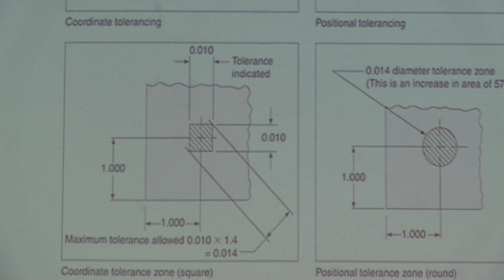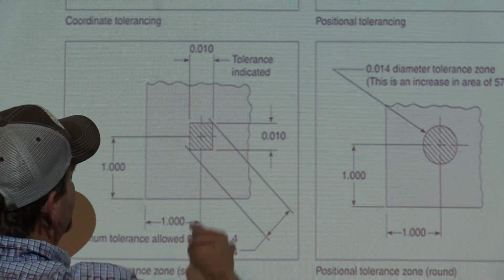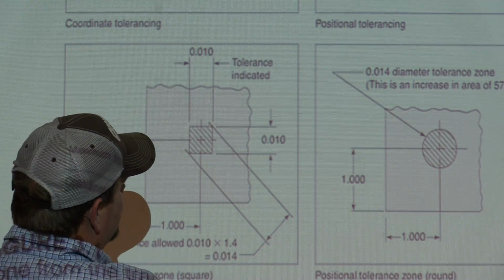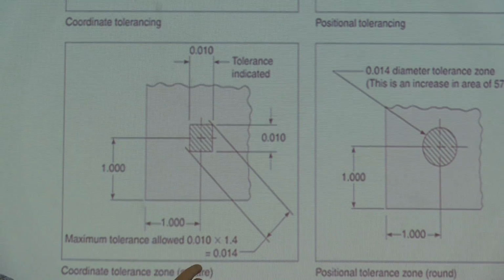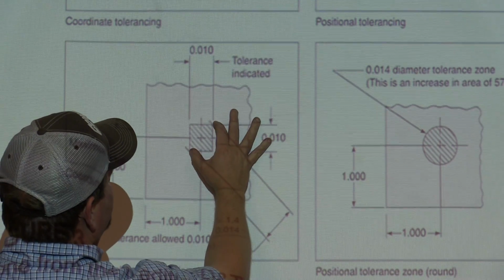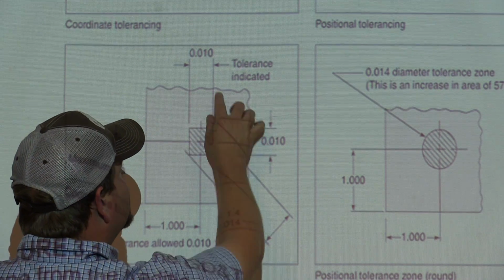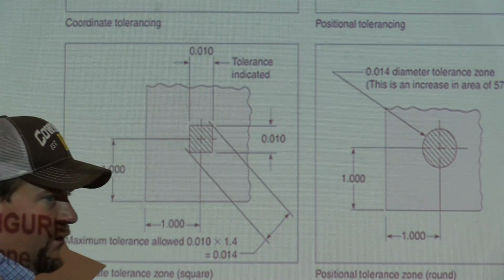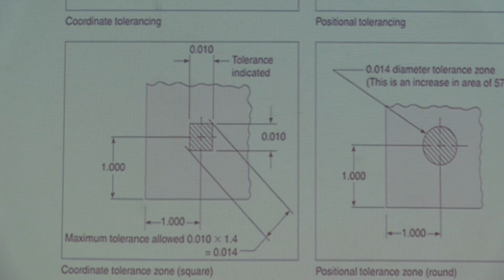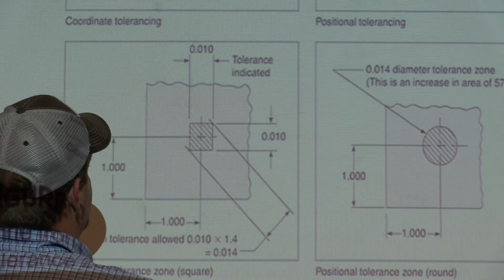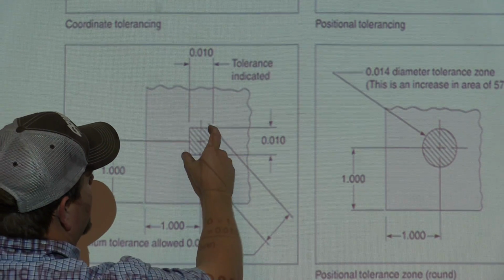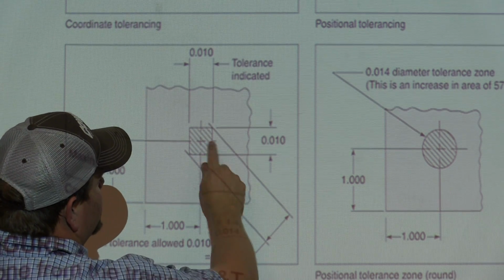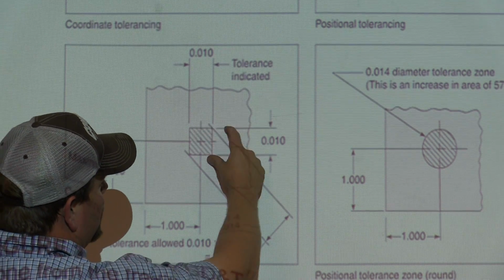Now why is that? What it's saying is that you can be anywhere within that zone and you're still within tolerance. However, the measurement across that square is greater than 0.1. It's actually this times 1.4142 is the correct dimension. So your tolerance can also extend into this portion as well. In this case it's a square dimension.